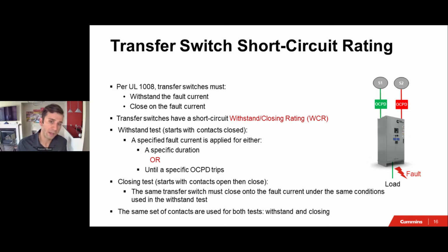So now it closes onto the fault, because whatever caused that fault hasn't vaporized yet. Transfer switches get their rating in what's called withstand and closing rating. So they withstand the fault and then close onto the fault. And this is all outlined by UL 1008.